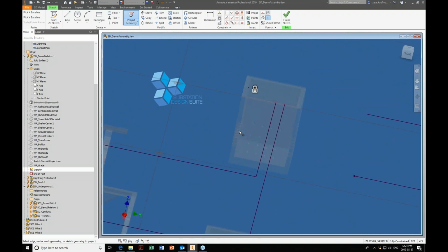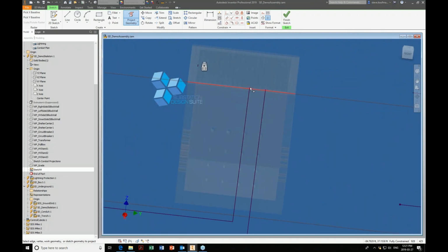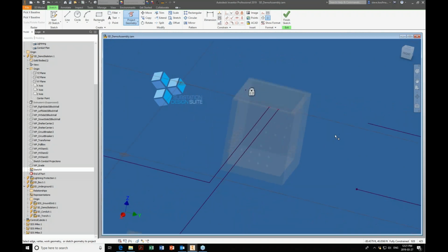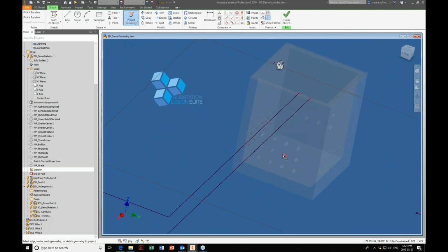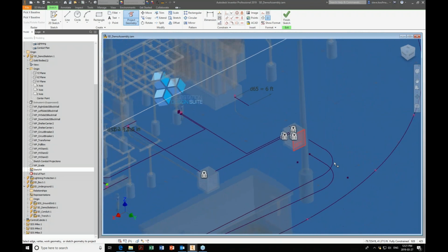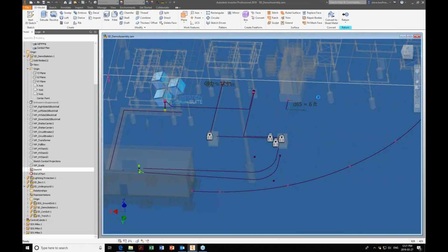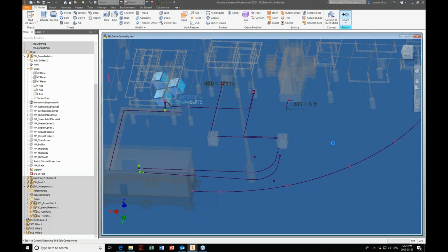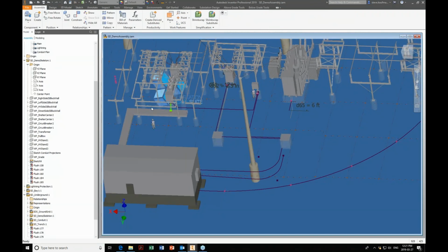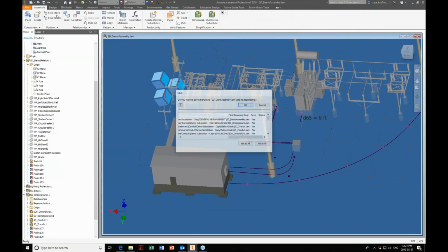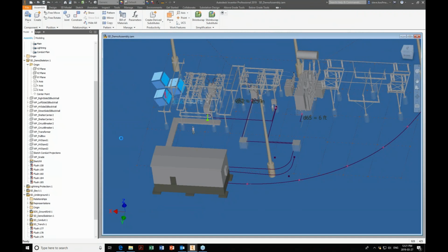Here I'm going to bring in another one. Over here you can see already some have been added, so I'm going to leave those here. We already have those in here, but I can bring them in again because it's a different sketch. All right, so we have that information in our skeleton. We can finish that, return, and save our model. Always remember to save.